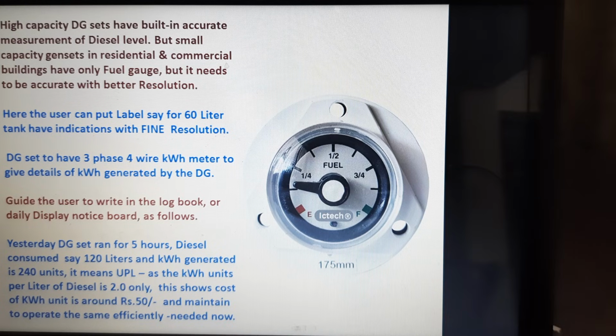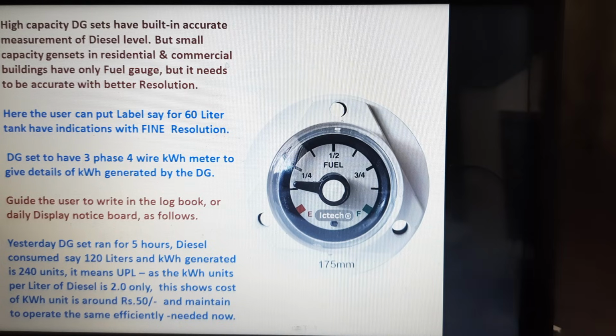Say for example, yesterday the DG set ran for 5 hours and diesel consumed is 120 liters. Let us say the kWh generated is 240 units; it means the units per liter is only 2. So almost rupees 50 is spent towards 1 unit of electricity, and the DG set needs to be maintained as well as operated efficiently. That is more needed now, especially in the residential and commercial building segment.